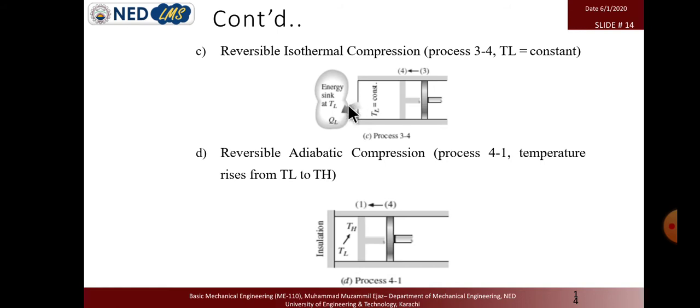So due to that, the temperature will also decrease in the system, but we need to keep it constant, this is isothermal compression. So to maintain the temperature constant, the heat released from the system goes to do work, and the gas will compress. The temperature will not reduce, but the gas will contract and the volume will decrease. So this is the isothermal compression.